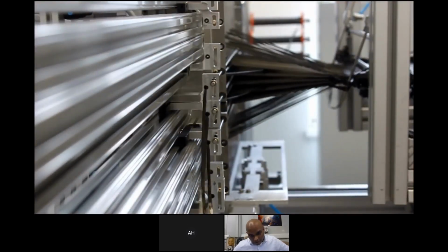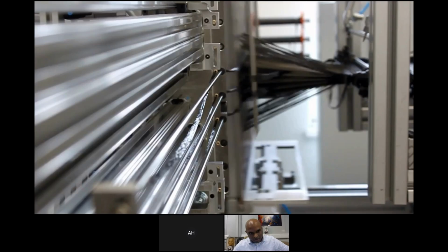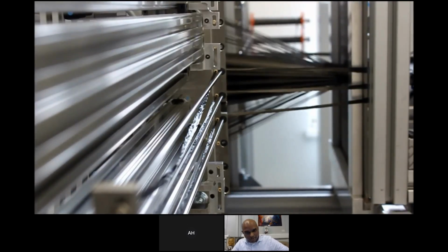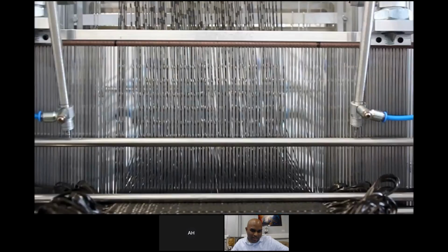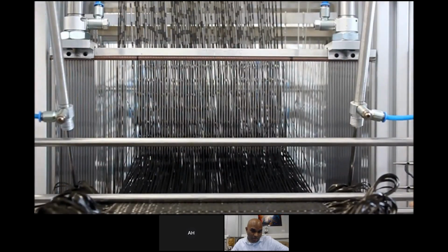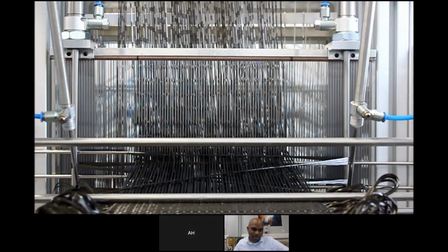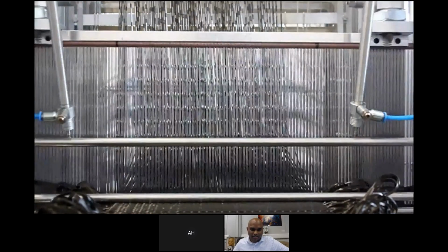An elegant way to solve this problem is the patented weaving system. As you can see in the video now, we developed this in this SimCom Hub project. We can put 22 wefts simultaneously in this system, and we further modified this robot to incorporate off-axis fibers. We can make near-net shapes as well, such as T's, Pi's, and I's.